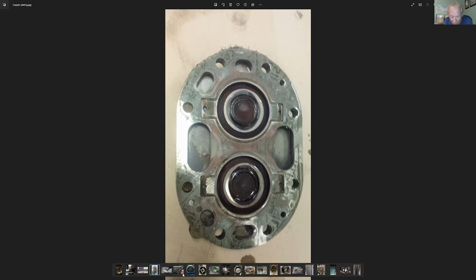And you can see on those discharge pucks there, that's some yucky looking stuff. And if it's got the yucky looking stuff there, is it seating and sealing correctly? Potentially not, right? Same with your reed valve too, which is not shown in there. It's missing in the picture, but are they sealing correctly? You need a thin film of oil there to help seat that every time it opens and closes, and you don't get the blow by.